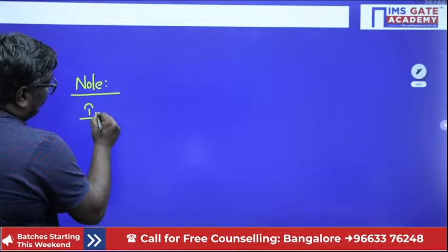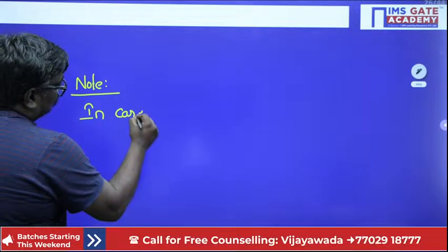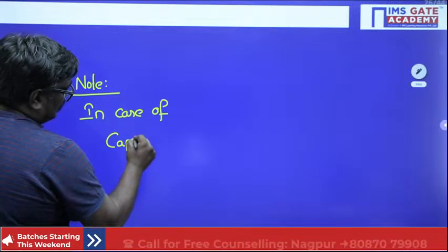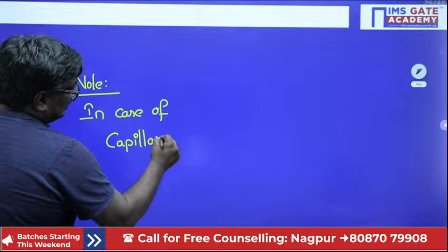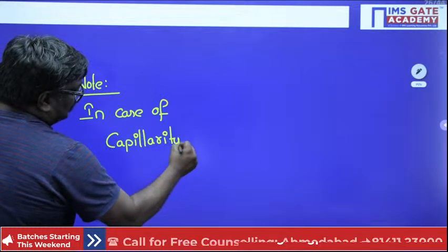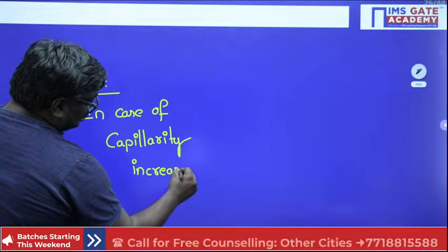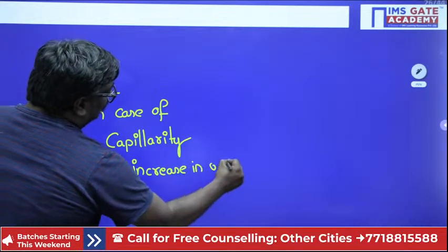In case of capillarity, what is the increase in effective stress? If anyone asks you what is the increase in effective stress, I am giving you the shortcut also.